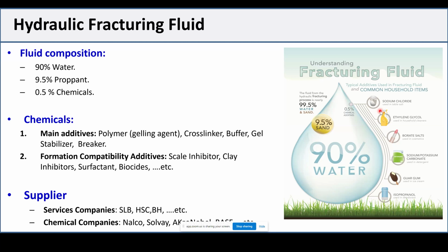That depends case by case. However, the majority of crosslinkers are high pH crosslinkers between 10 and 11. There is also some marketing for low pH hydraulic fracturing, and usually the target pH is around 4 if you have a low pH cross-linked fluid.